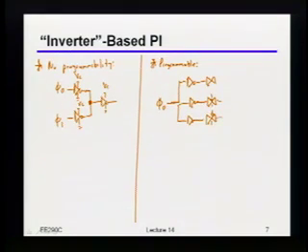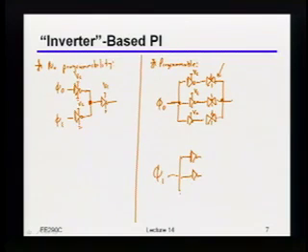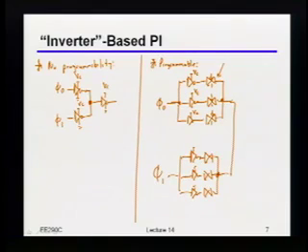Okay, and just as a reminder, for those of you who don't remember from 141, that funny-looking symbol I drew right here is just a transmission gate, right? So it's a PMOS in parallel with an NMOS, with the digital control set by opposite bits. And just as a reminder, the supply of all these is the control voltage. I then take the same thing and put it on phi 1. Again, I'm going to be programming those tri-states to decide how many of them turn on. And then I just tie those outputs together and buffer it out, and I'm done.